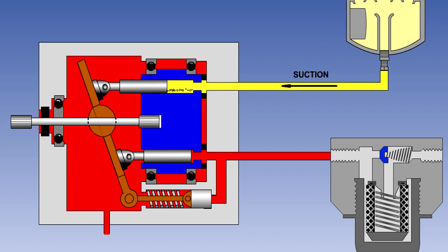When these bubbles pass through to the pressure side of the pump, they then implode with great force. This is known as cavitation, and if allowed to happen, it can cause severe damage to the pump. The sound of pumps operating while cavitating can range from a low-pitched, steady knocking sound, like on a door, to a high-pitched and random crackling, similar to a metallic impact.